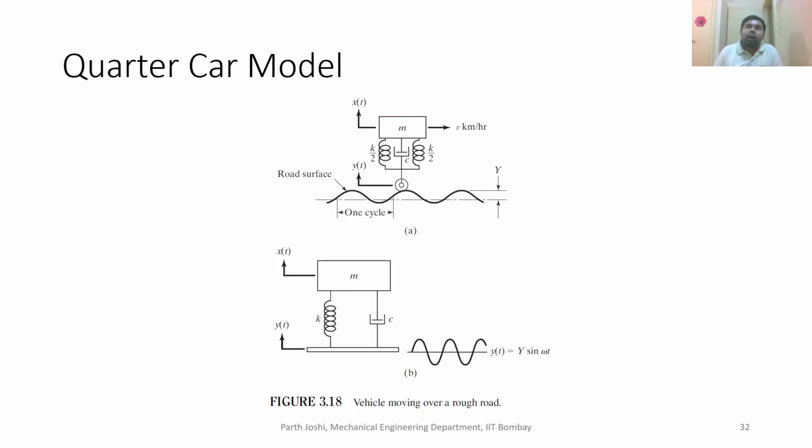Then on which part of the road the tire is coming into contact with, so you define x of t as the vertical up and down movement of the car body. You call it x, and the extent by which the wheels are moving up and down, you can call y of t. Because of the presence of suspension, which is the spring and damper shown over here, we will feel less jerks as compared to if it was just a rigid thing going over the road.